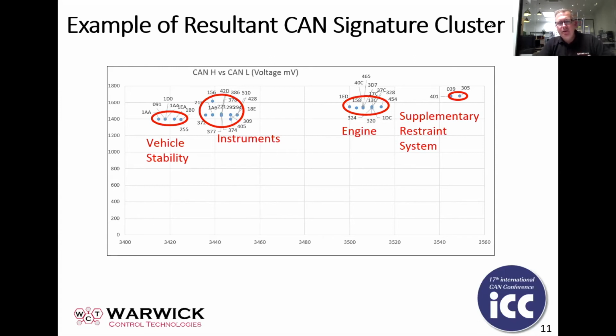And so effectively, each CAN message signature is basically the average of the data field dominant signals of each message on the CAN bus. So you can see we group these together. Because we have the CAN specification of this particular vehicle, we were able to confirm this.